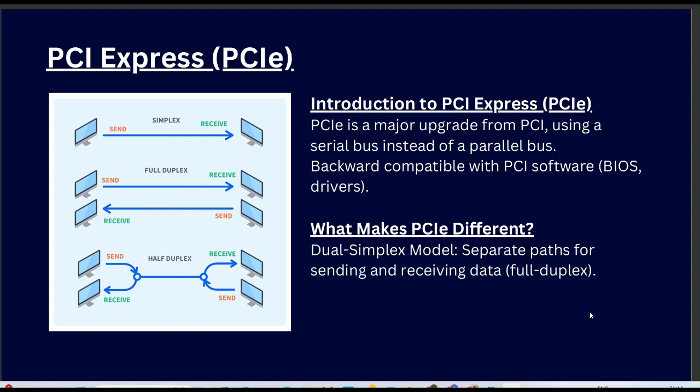So PCI was parallel, and PCI Express is a serial protocol, more like Fibre Channel. Although it is based on a serial model, PCIe is fully backward compatible with PCI software, making it easier to integrate with existing systems. That is, some devices still work on PCI systems, so PCIe should be compatible with PCI software also.